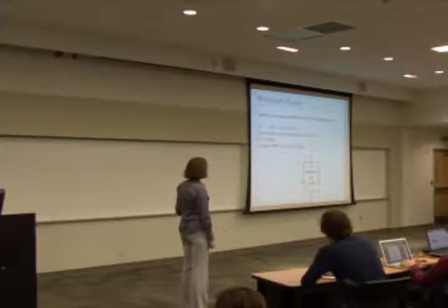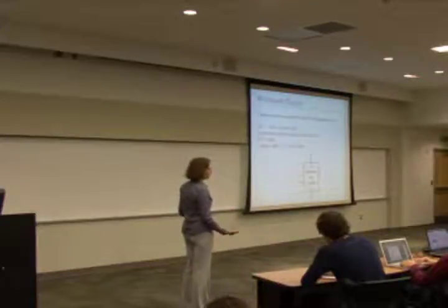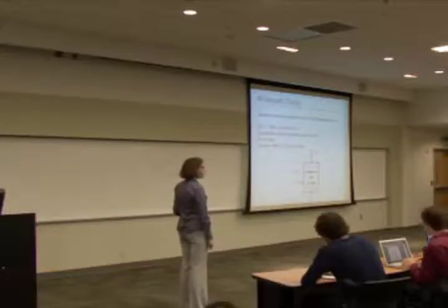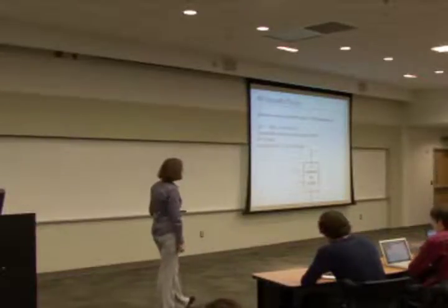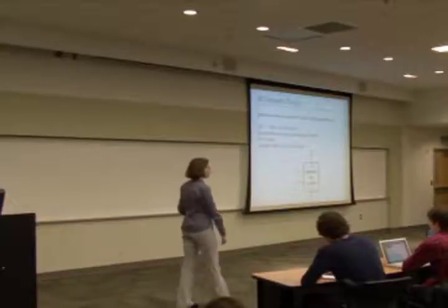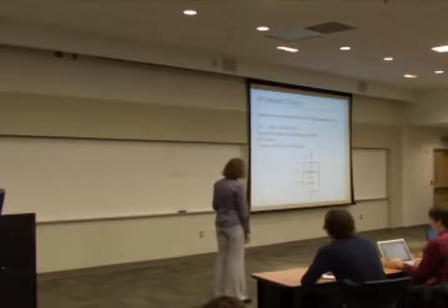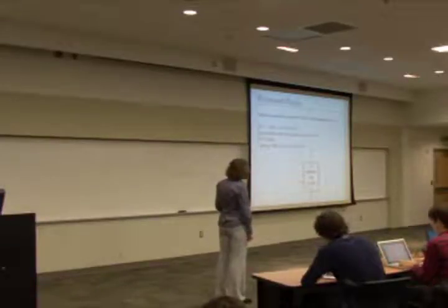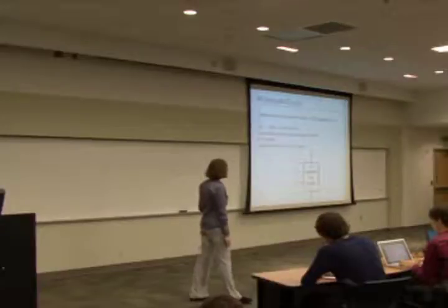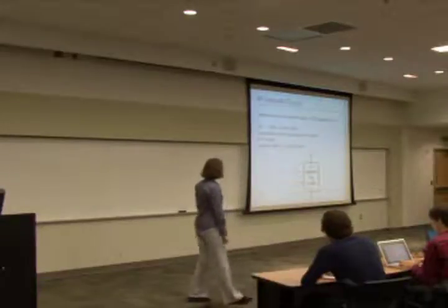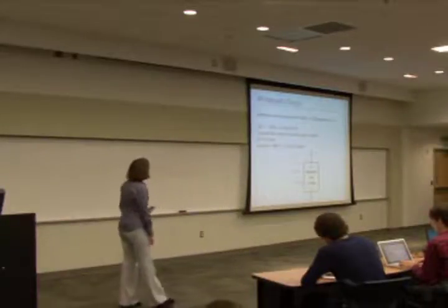So if it's 0, that means we are not writing anything. If it's 1, we are writing something. How many wires is that? And this register number, or regno, that's basically register number. So if we have 16 registers, how many bits do we need to represent? So we need 4 of them. So that's description of that.